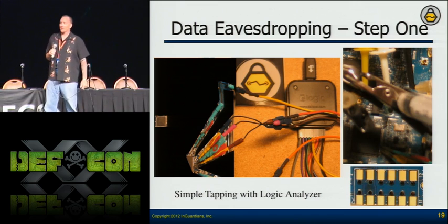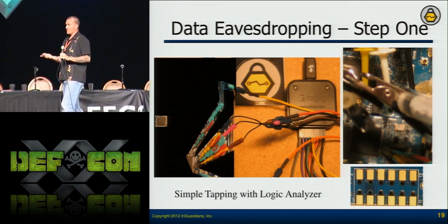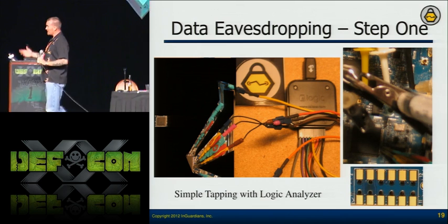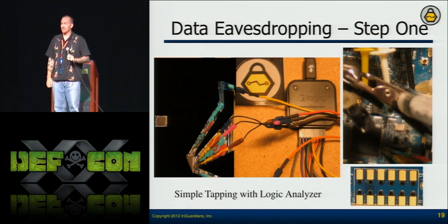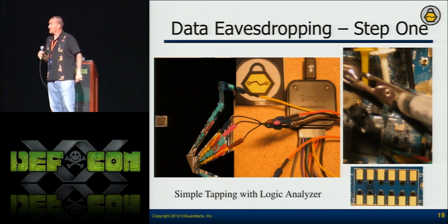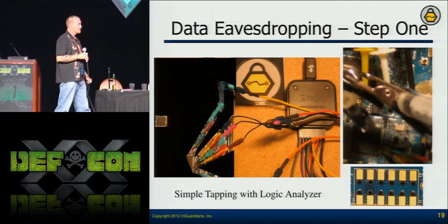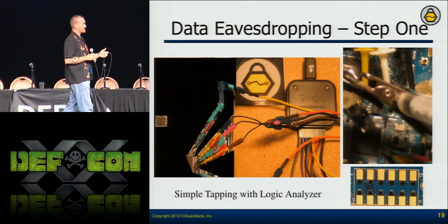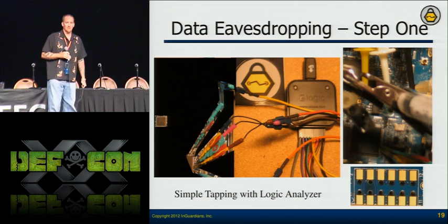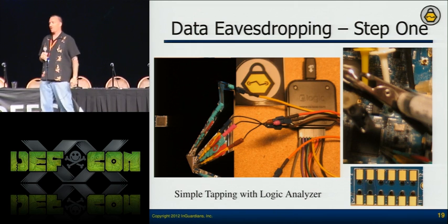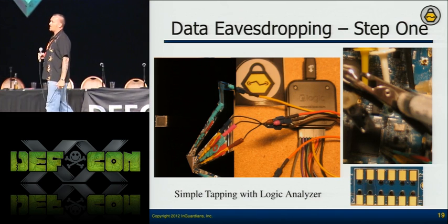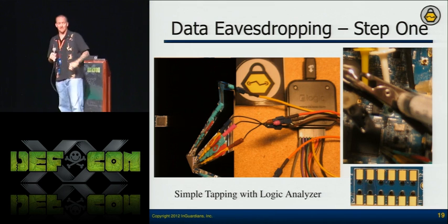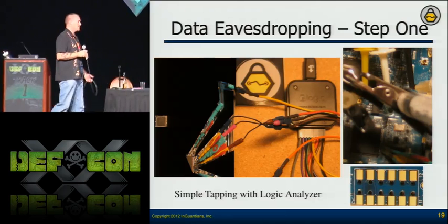On the right-hand side, if I can't get the micro grippers on there, if it's something like the BGA (ball grid array) components, or they're really small and I can't get the grippers to grip on, then I'll tap with the hypodermic needles. It's really good because it's got that point and it'll grip on there. But the problem with both of these things is that if I tap this with my elbow or my knee when I'm standing up to go do something, all of that stuff pops off. You don't know how aggravating it is to spend 30 minutes getting those hypodermic needles on there, just to look up, bump it, and have to do it all again.